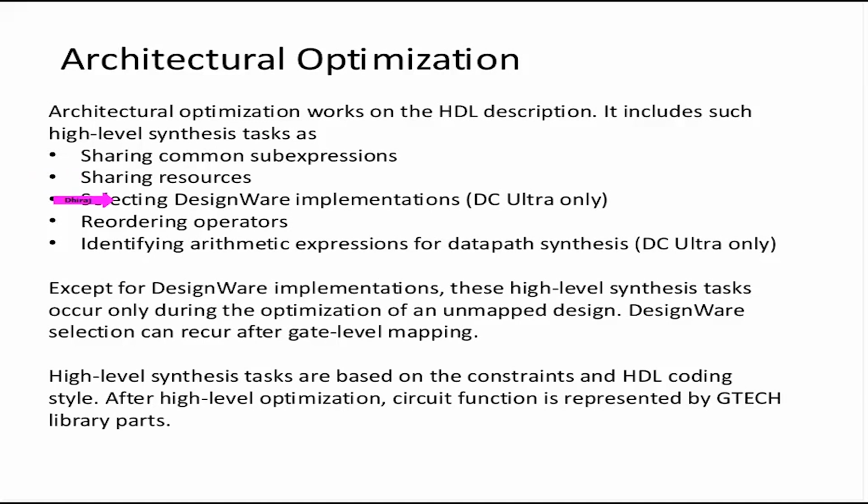It will also make decisions about what DesignWare components and what DesignWare implementations to pick up. For example, for an adder, there are multiple implementations like a ripple adder, a carry look ahead adder, and so on. So it will do some sort of implementation selection. When we say implementation, the DesignWare component would be an adder, and the implementation can be one of ripple, carry look ahead, carry save, and so on.